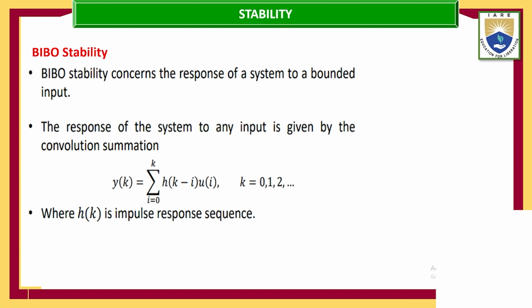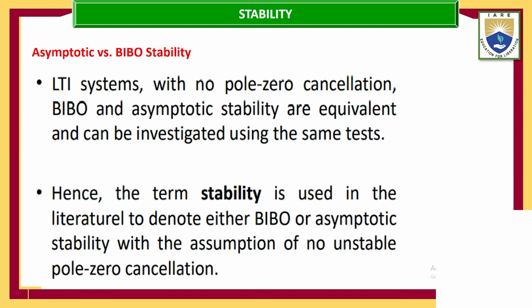Now, what is the difference between asymptotic stability and BIBO stability? Generally, in the case of LTI systems with no pole-zero cancellation, BIBO and asymptotic stability are different.